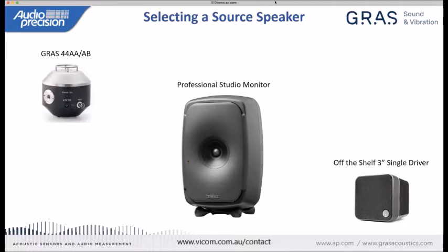As far as just using a regular speaker, which is a completely valid choice, the main issue that controls is the frequency range of interest and the sound pressure level that you're looking to achieve. By the frequency range of interest, I mean if you want to measure the frequency response of a microphone from 20 hertz to 20 kilohertz, well, it can be equalized, but you can't equalize from 0.